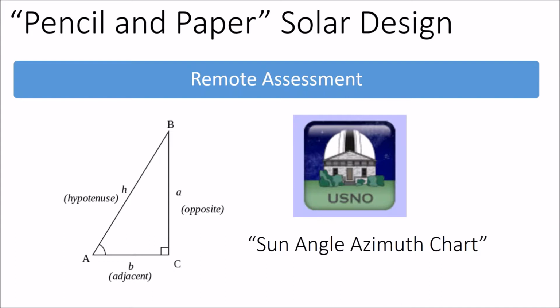And that would be problematic because a little bit of shade would mess up the power point tracking, confuse the inverter, and it would curtail its output rather substantially. So on a partly cloudy day, or if you had a little bit of shade on your solar array, that would wreak havoc on solar production.